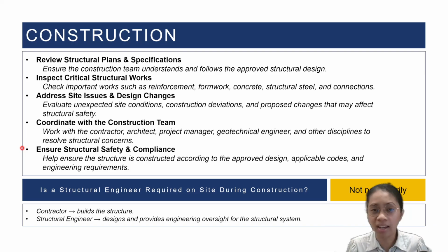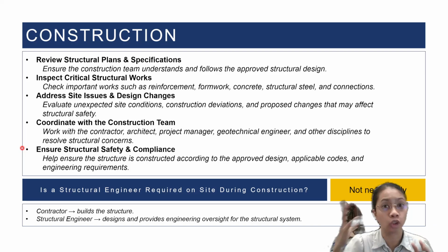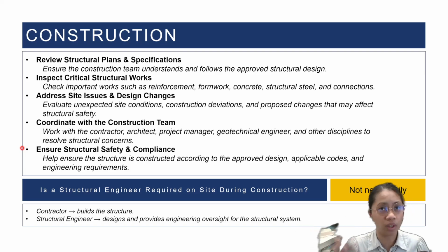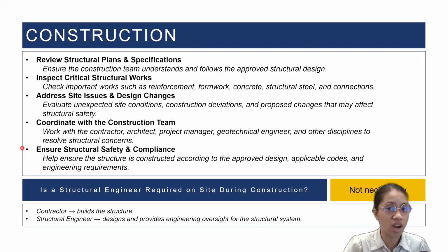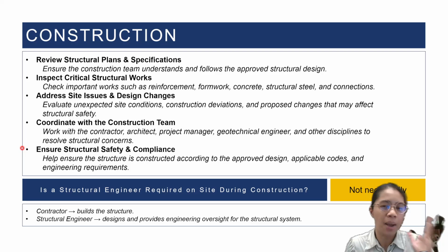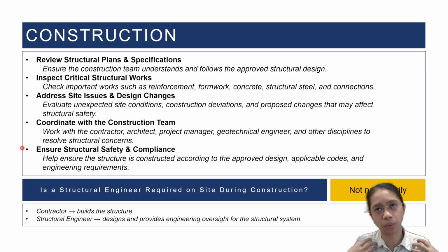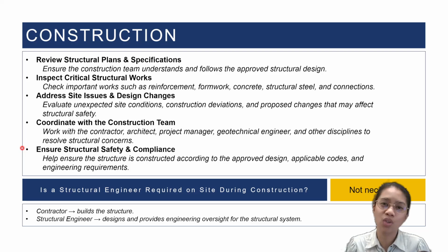And if someday the building collapses because of that wrong construction not in accordance with the design, made by the contractor, you will be liable as the structural engineer. If you were asking, ma'am, how about the contractor? I designed well as a structural engineer, but then the contractor is the one who didn't build it. Both of you will be liable because you signed it at 12 columns and then you didn't visit it on site. So once in a while, as a structural engineer, it is your responsibility to check your design if it is actually made on site.